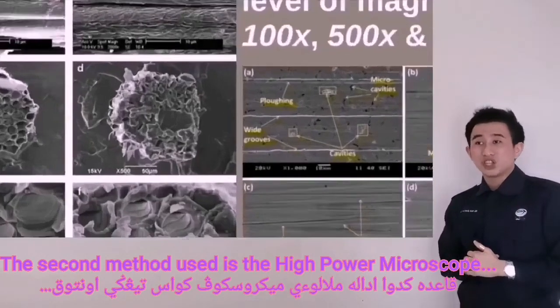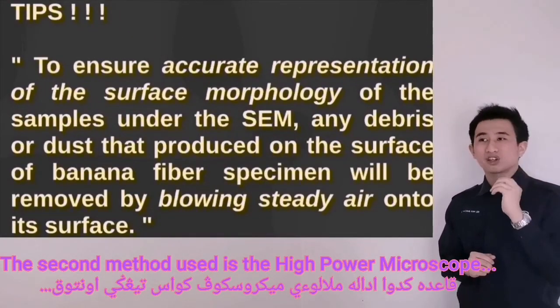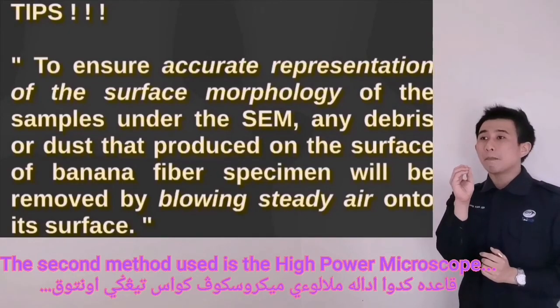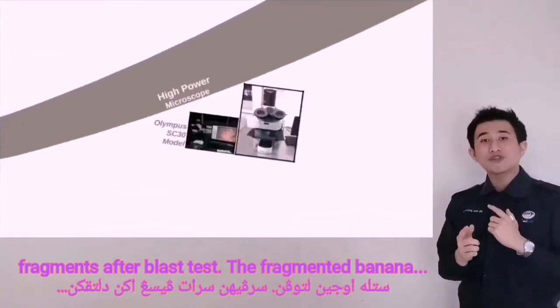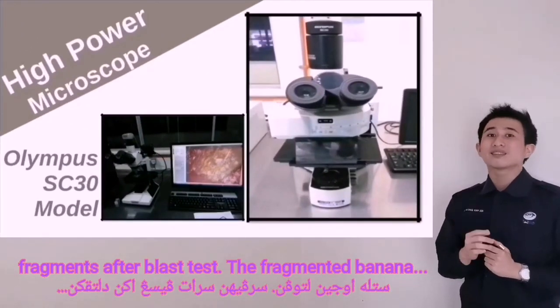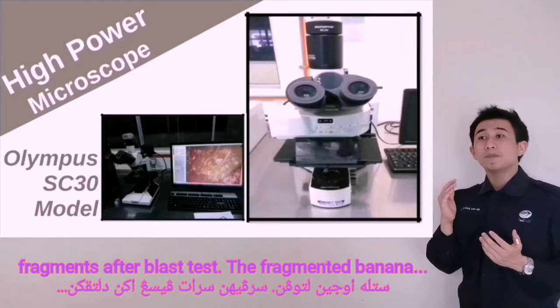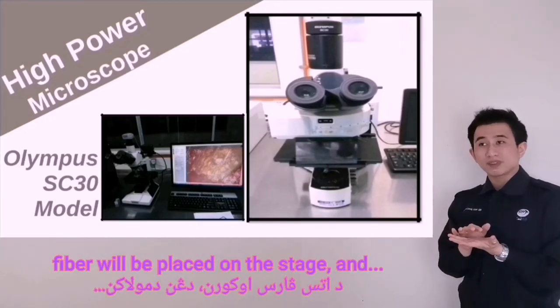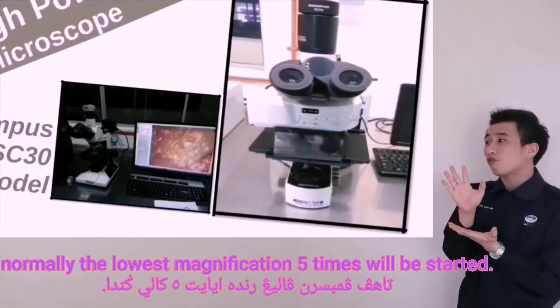The next method is a high power microscope to see the microstructure of the banana fiber fragments after the blast test. The fragmented banana fiber will be placed on the stage, and normally the lowest magnification of 5 times will be standard.